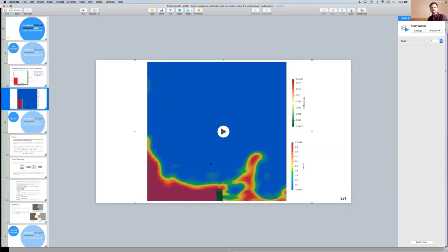The only thing that's custom in Solids4foam is basically the boundary condition, where we transfer the velocity of the solid to the fluid. At the moment, that's actually done within the fluid-solid interface class, though my plan is to extract that into its own point motion boundary condition to make it more independent. And then for the solid models themselves, it depends on the formulation, but because they're Lagrangian, the mesh motion isn't independent. Once you solve the equations, you automatically get the mesh motion. So you don't really have a mesh motion solver.